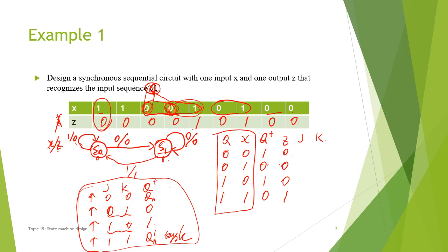But it can also be like toggle, right? So actually there is no reset because it's from 0 to 1. It can only be either toggle or set. So no reset here, sorry. So which means J has to be 1, but K could be 0 or could be 1, which means we don't care about K. Whatever value it is, this change will happen.